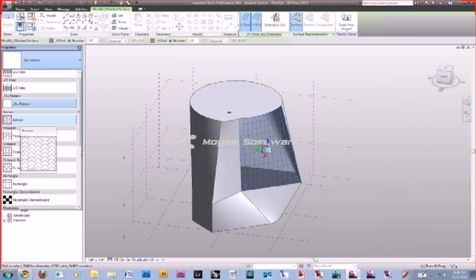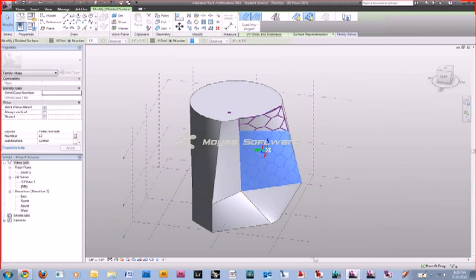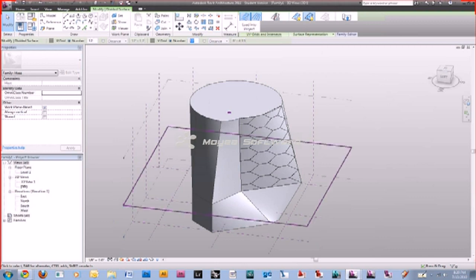So if I choose a hexagon, now it's sort of a hexagon shape. But what these hexagons entail is you can make a custom component for each one of these hexagons. And these hexagons will change and adapt depending on your spacing and your sizes for these. So instead of 12 by 12, we change this to a 6 by 12 or something like that. It will change the size of those. And the idea is to create a component that would fit inside these perfectly. And they will also change and adapt to the surface itself, as well as the spacing that you imply.